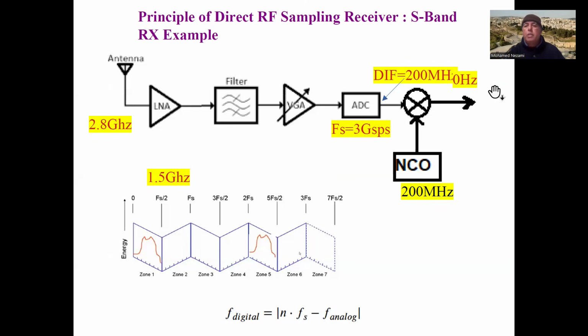Now, in some cases, the DMOD in here will have a feedback to the NCO, because a lot of times if you're dealing with a Doppler shifted signal, or a signal that has some kind of frequency inaccuracy, or you want to translate it to another frequency, you can always feed it back here and do the tracking in here.